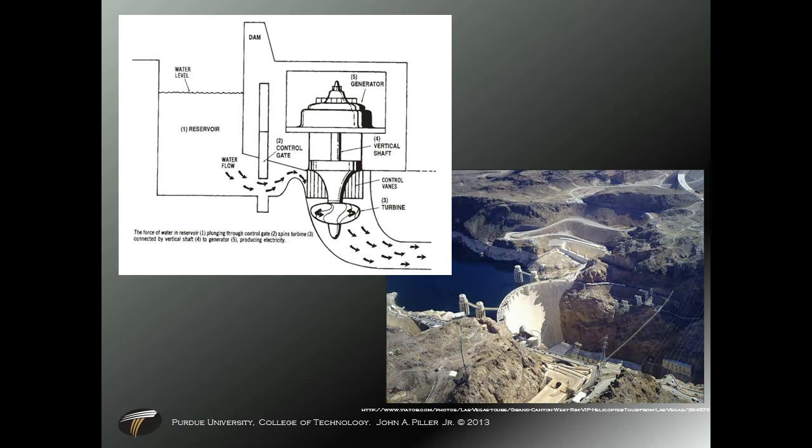I did say we're carbon neutral. However, we're carbon neutral after methane emissions are gone. Methane emissions from a hydroelectric dam come from the decaying plant material that's under the water. There was trees and bushes and grass and all those things that got flooded under Lake Mead. That decaying plant material is now in an anaerobic environment, and in an anaerobic environment, that means there's methane output. Methane output will go for years until all of that organic material is fully decayed, and methane is a greenhouse gas.